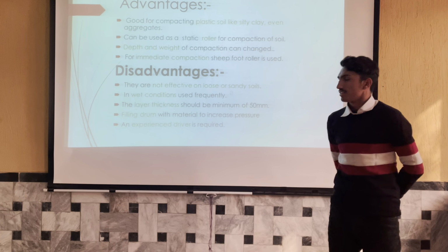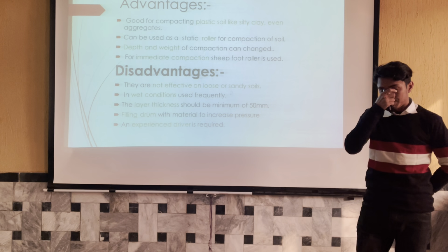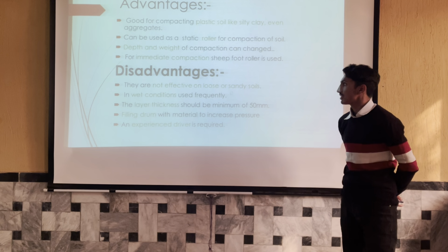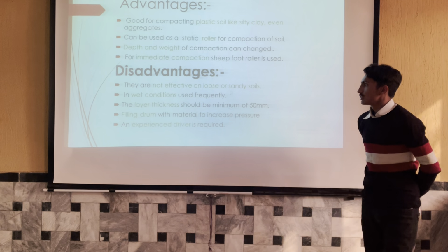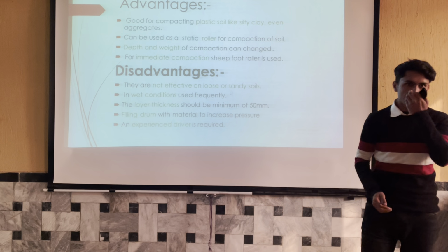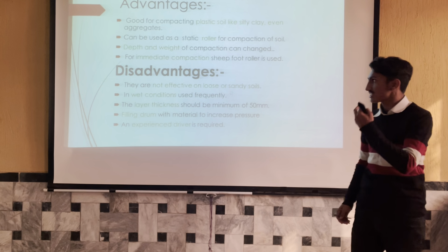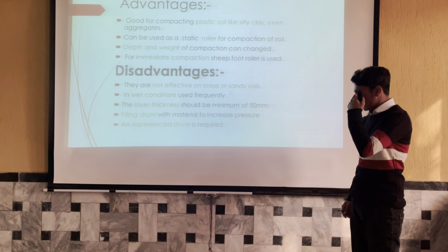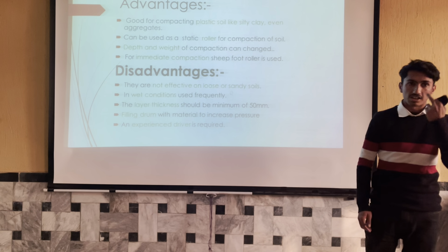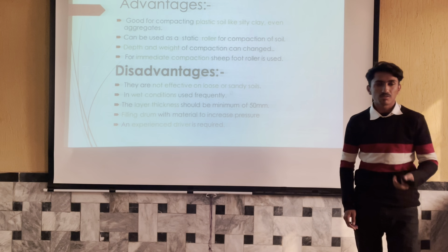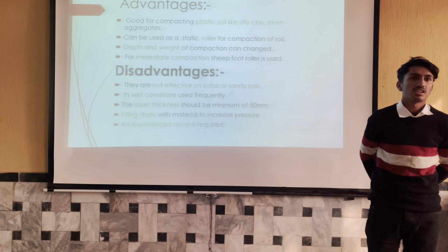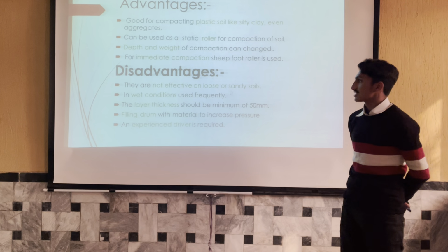Disadvantages. Because of a few variations in the design, we have some disadvantages as well. First of all, they do not compact loose or sandy soils, because those have low moisture content, so instead of compacting the soil, they start tilling.